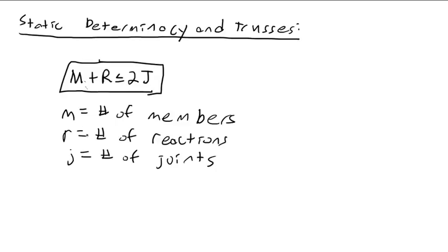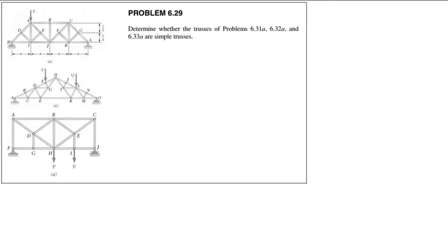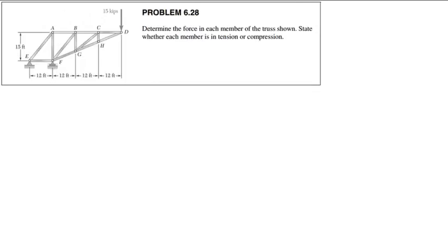Okay, so that's the basic idea. Now, this would be a similar idea. We could go through here and, oh, actually, I like this one, 6. Yes, this is one with all the zero force members. See, in certain trusses, you can get what you might call a zero force member cascade, where things just jump from one to the next to the next.